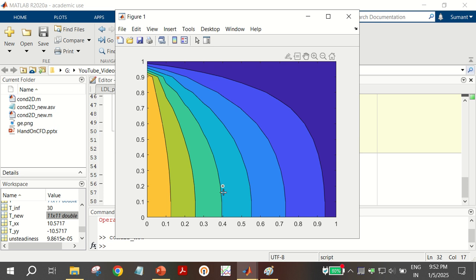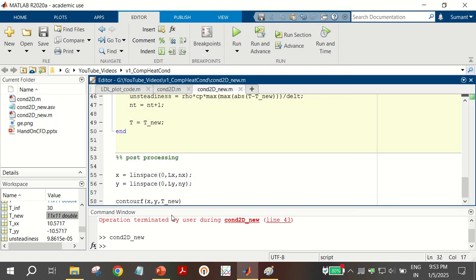If you take the slope, that will be 0, because there is no change in the gradient. So insulation means dt by dx is 0. That is what is being implemented. And here also you should ideally get some lines, that might be because of the number of levels. It is a constant slope because the heat flux is constant here, so qw. So that's the way.